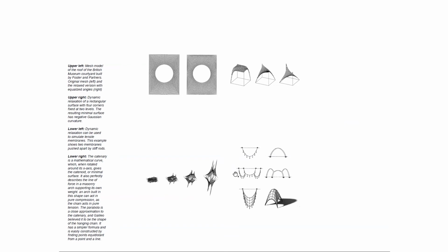These were some examples from last year from the students, from the same code that you will have a look at. So they started basically using the Python code that I will give you, and they were creating these tensile structures, and then they also integrated compression forces, kind of stiff struts in between them, so they start to stretch this fabric. So suddenly you can basically model in Rhino with these sort of forces. So it's almost like you have a stretchable fabric in a computer that you can play with.